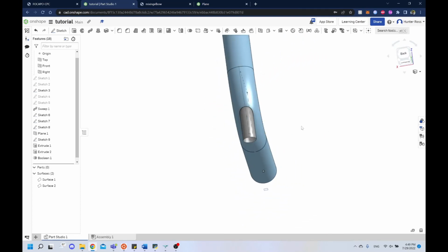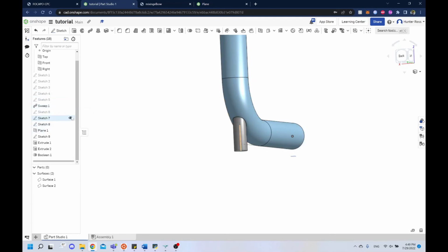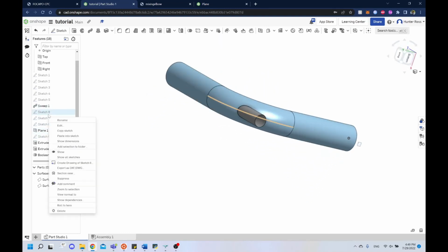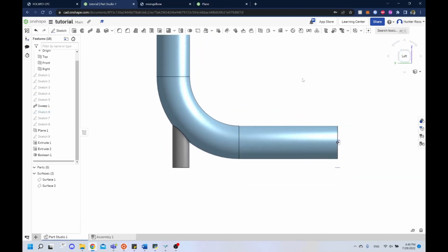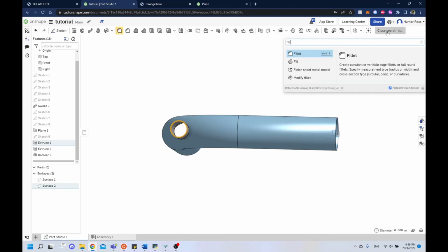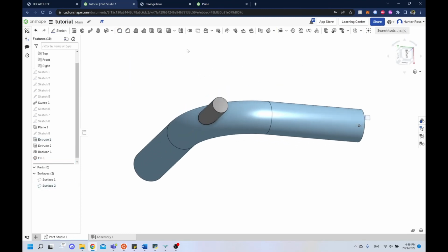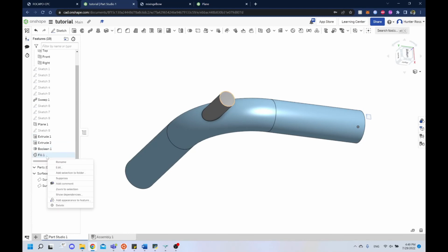to do that, what you can do is first, let me hide these sketches because they're distracting. There you go. And I think you can also click hide all sketches. No, that's a Salome feature. Sorry. So let's fill in these holes so that it's waterproof. So what we'll do is we'll select this circle, and I forgot what it's called. So we're gonna do this, and it's called fill. We're gonna add. You'll notice there's two options there. Sorry, I kind of breezed through that.